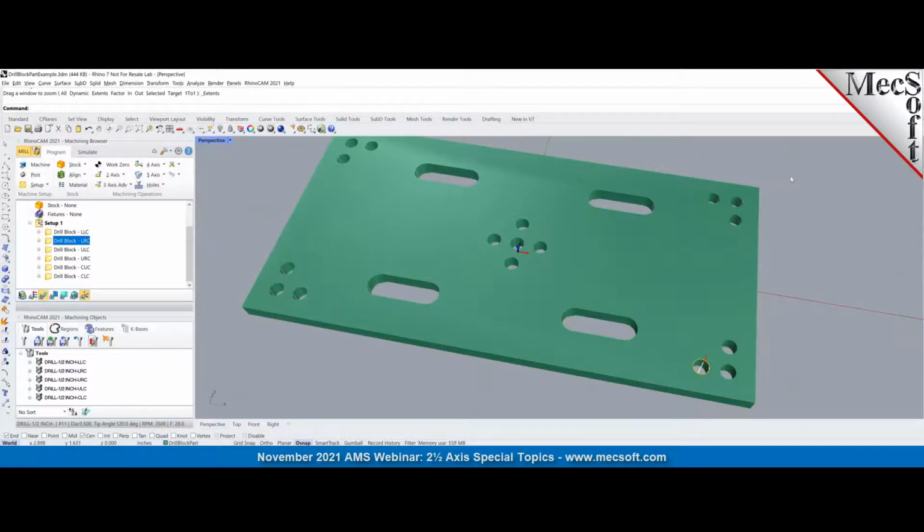A couple of caveats. One is a hole pattern like this on the top right corner. Let's call it the upper right corner. What we have here is 3 holes, but the anchor hole is not being drilled. So the lower left corner is not being drilled. Even though it's not being drilled, in our CAM system we have to create an operation that actually creates a drill toolpath that goes right there. So that's why I've created this circle to represent the location of the anchor bit, and I've created my drill operation to drill that hole.